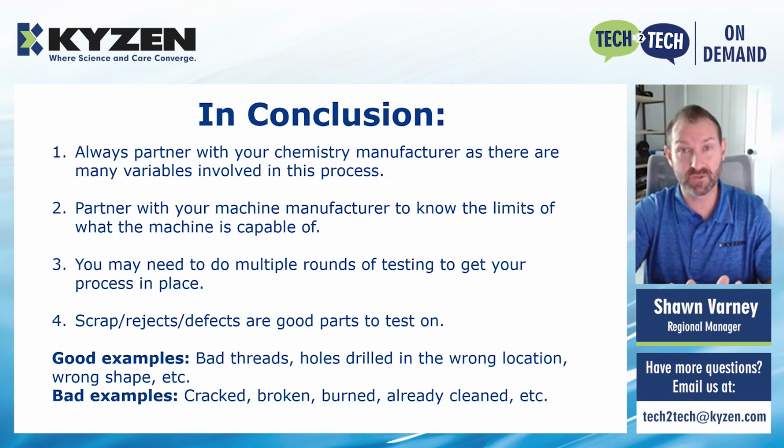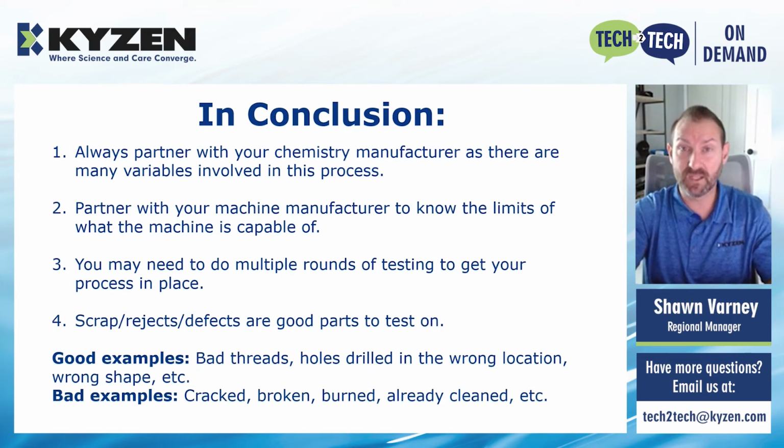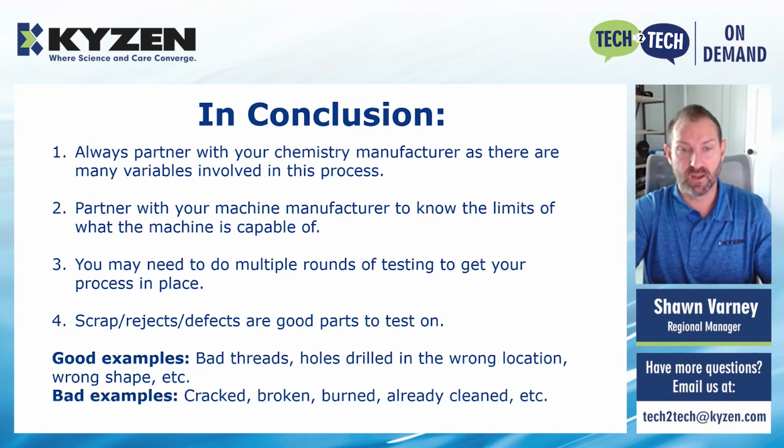Bad examples that you don't want to use would be something either cracked, broken, burned, or already cleaned. So if it was already cracked or broken, you wouldn't know if your process or your temperature affected or caused that. Burned, or that discoloration or corrosion, oxidation, you want to know that before it goes in. You want to make sure you have a good part. Already cleaned, so the cleaning chemistry, maybe cleaned it with a different chemistry. You want to make sure that there's not a reaction between the old chemistry, maybe it wasn't rinsed off enough, before you reused it again and did some testing on it.